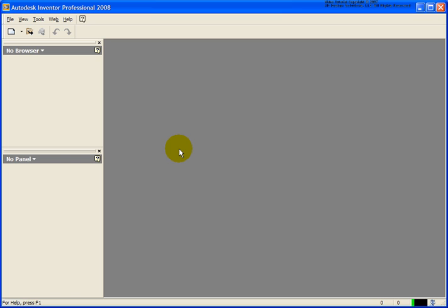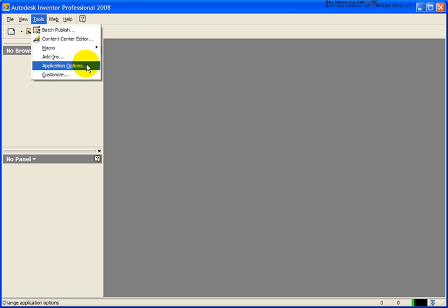In this lesson, we will be taking a look at how to create a brand new drawing and how to set up a drawing once that is created. We're going to start off by taking a look at the application options. So from the Tools pull down, I'm going to click on Application Options.